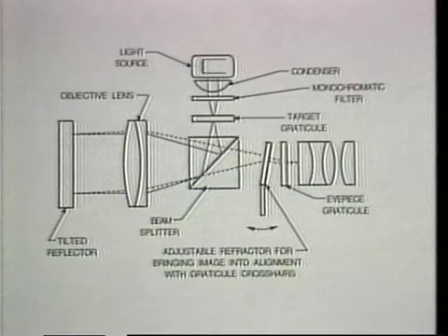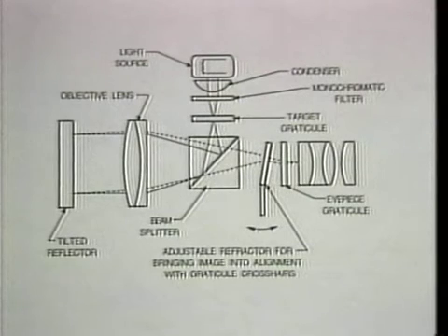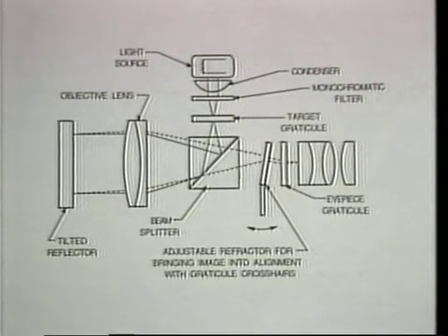Originally, the reflector's angular deviation from the orthogonal orientation was determined by the amount of rotation of the refractor element required to bring the target's crosshairs image into alignment with the graticule crosshairs. The refractor element would be manually or sometimes automatically rotated until the graticule crosshairs and the reflected image were aligned, and the angle would be read from the calibrated rotation mechanism.